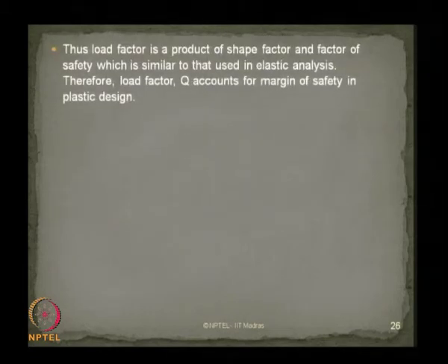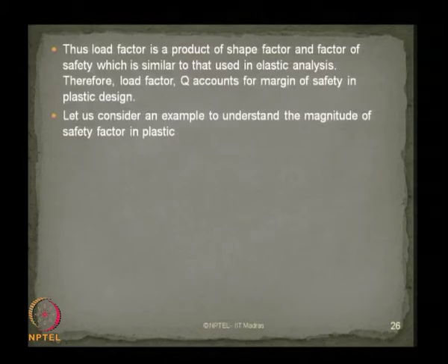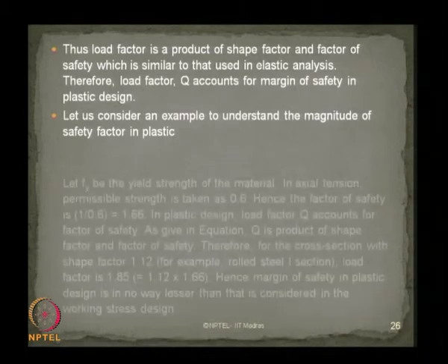Thus, the load factor is nothing but a product of the shape factor and the factor of safety, which is similar to that used in elastic analysis. Therefore, a load factor Q, which accounts for the margin of safety in plastic design, can be considered as a margin of safety like the other design factors you see here. Now, let us consider an example to understand the magnitude of the factor of safety in plastic design.